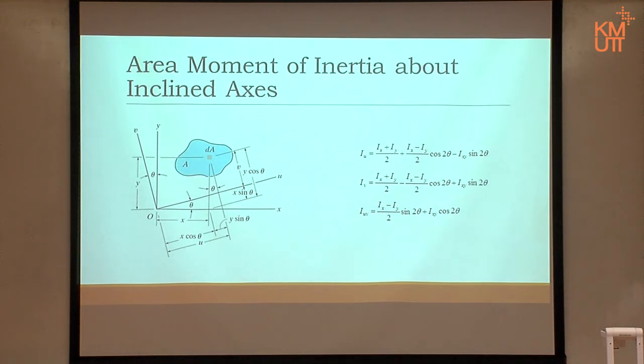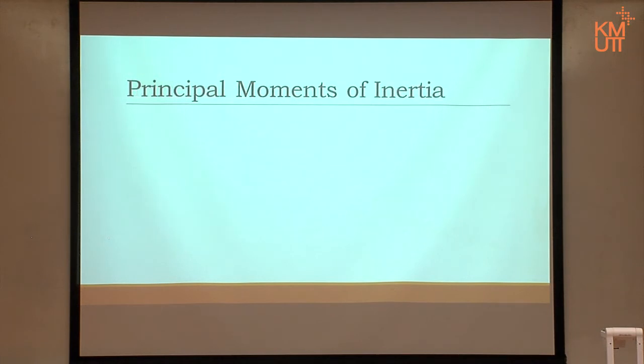And you can guess, if there's a max and a min, then we have to find them. Apparently, the axes of the max and the min are where what we call unsymmetric bending happens. Then it becomes something that we have to find, and that's why we keep using symmetric cross-sectional areas if we can.